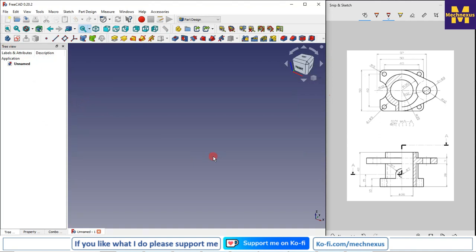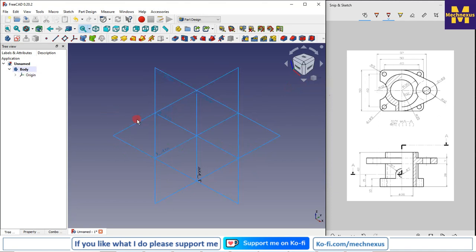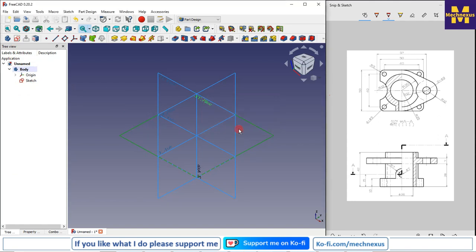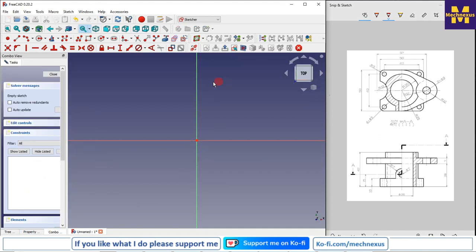First we will start reading our drawing. We can see that it is a 50 by 50 square block. So I will create a body, select my base plane XY, and create a sketch. I will turn off my origin plane and draw a rectangle.